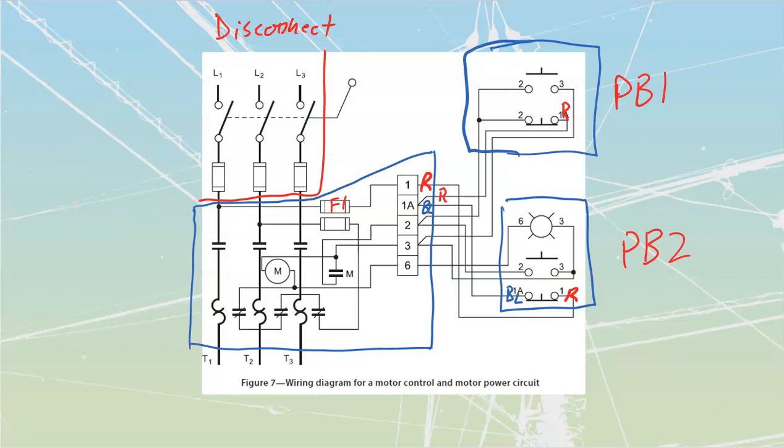I go back to this drawing over here, or to my control box over here. I'd actually have the drawing with me as I'm wandering around doing this. I see that that conductor that goes between those 2 points also has another conductor that is leaving from that box. So we have a red conductor coming in. We're going to say that this one's going to be my blue conductor over here. So I'm going to track that blue conductor down, and if I follow that blue conductor down, I see that it goes to a terminal number 2 inside of my switch over there. So I'm going to go and do that.